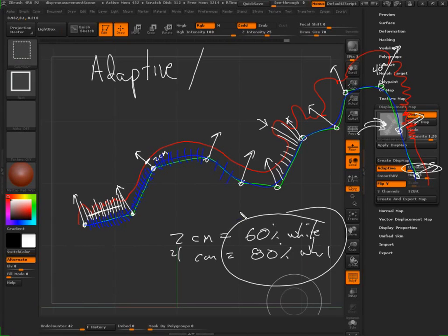If I set it to 3, then that all gets quite a lot more intense, right? And if you set that DP Sub Pix to 6, well, now you can imagine you've got a ton of vertices shooting out and taking up an enormous amount of time as they calculate the displacement map. And some of that is waste. Some of that is totally unnecessary. It is a brute force approach.